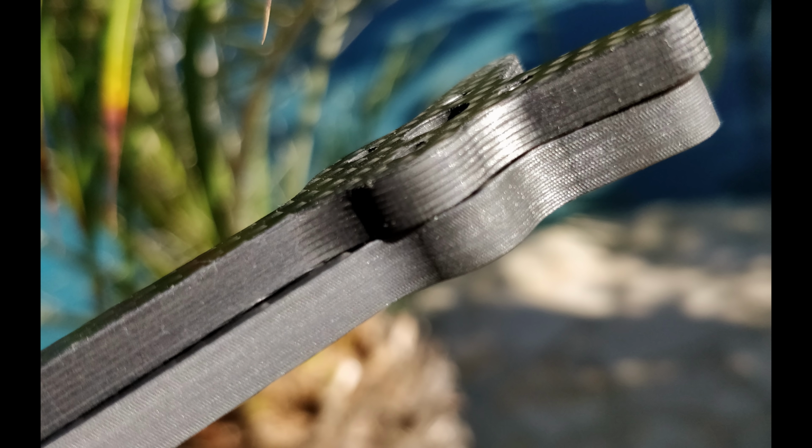Interesting. Now we're getting to a point where I'm not sure what I can talk about, because I'm not sure what's official or not. But you can make a product that is possible to infuse that is way thicker. But then you have to custom make or modify the process to get the resin in there. You can alter the shape of the fiber or how it's arranged, so you get channels through it to get the resin in there. Exactly. Very interesting.